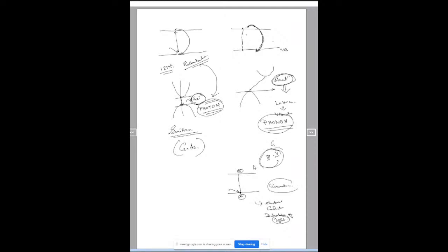So this is the generation process by light, optical generation. And the reverse process is recombination, where the excited electron comes back to the original band, releasing the energy in the form of a photon, and this material can be an emitter. It can emit light in a direct band gap semiconductor. So in a direct band gap semiconductor, you see that there is a possibility of emission.